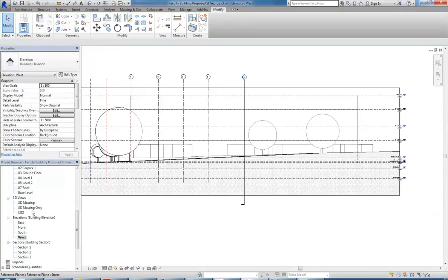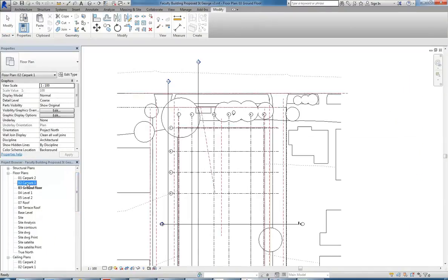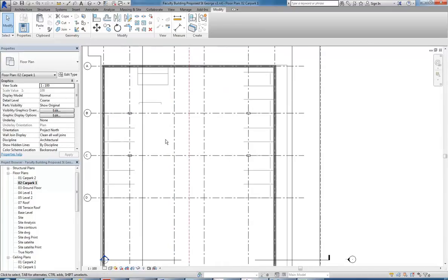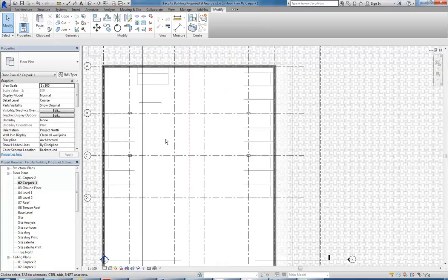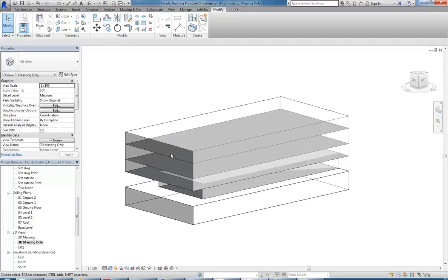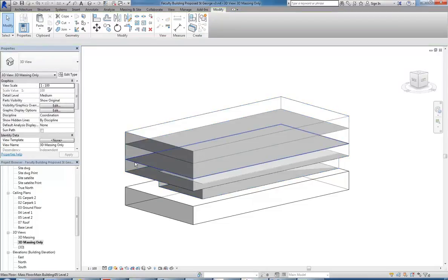Right, so then what you can do with the interior planning, as you start to work that out a little bit more, and then maybe just try and get an idea of the elements that you require and just lay them out in block form. Don't try and do all of that with one mass family, and that's where massing can cause some problems. So here I've got a mass family which is really just the envelope of the building I want. Notice how the floor plates have gone with the level changes that I made.